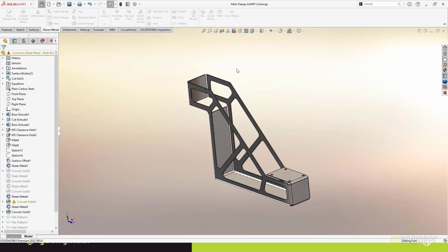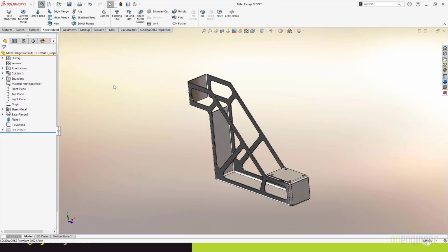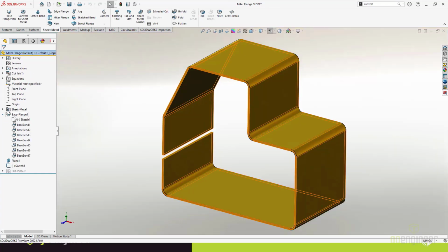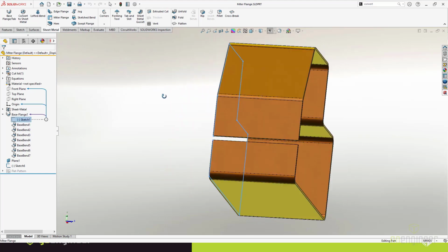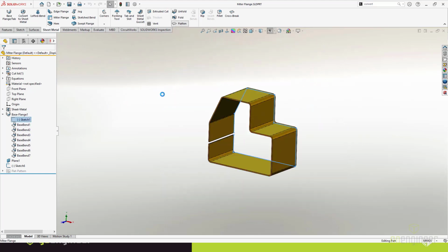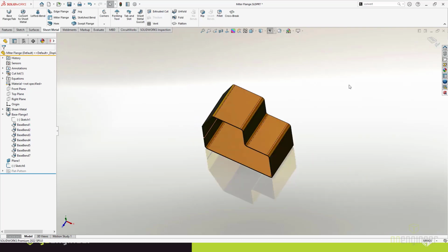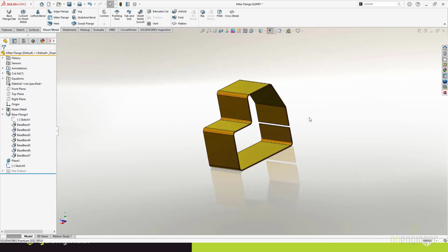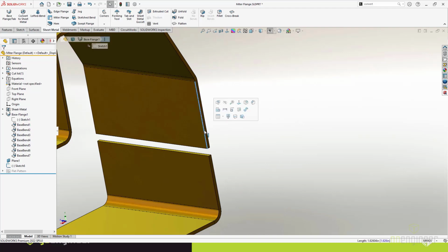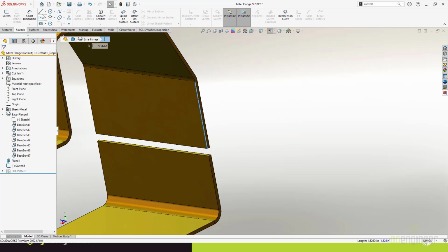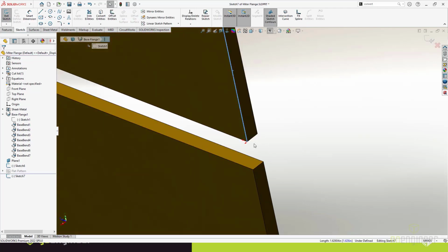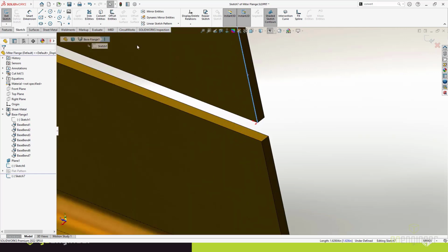You're looking at a part that's really just a basic sheet metal part. What I've got right here is a simple extrusion. That extrusion is just based on the most basic of sketches, and as a result, that's going to give us a basic flat pattern, right? Nothing really exotic to that. But if you were to come in here, pick an edge and start a sketch on that edge, which is a magical thing right here, by picking an edge and starting a sketch on there, it actually creates a plane right there at the end of that, and it creates a sketch for us.